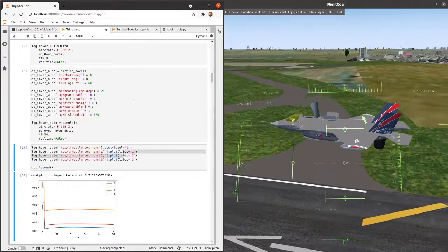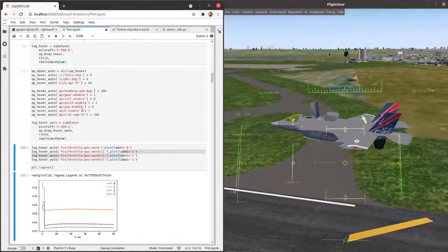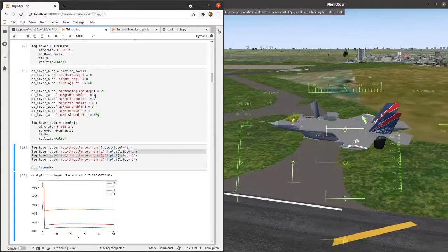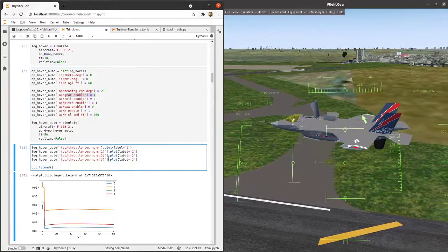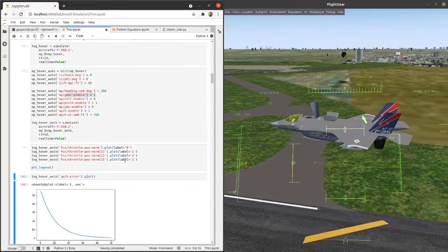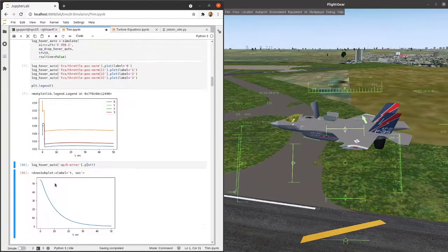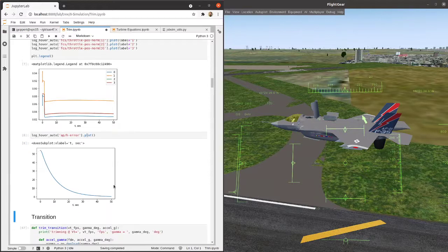Now this is enabling the autopilot for roll, pitch, yaw, altitude, and it also does auto gear deployment with the gear enable switch. Then we can look at our motor outputs and make sure that we're not saturating anything. You can see that they're all pretty high, around 80–90%. This is the step response in altitude.